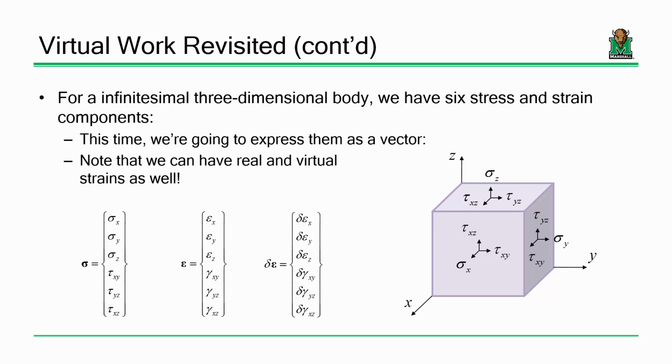Okay? Later on, after we've gotten through some of this theory and some of this computer implementation, I want to talk a little bit about how you actually analyze a 3-dimensional state of stress to get something from it that's useful to you as an engineer. Because it's complicated. That's not easy. If you've got some elements subjected to all sorts of stresses, how do you make some decision based off that? Like, has that element yielded? I don't know. That's tough, okay? So that takes some discussion in and of itself. And I think that's valuable to discuss, especially in this course, regardless of if you're going to be a civil engineer, or mechanical engineer, or what have you.